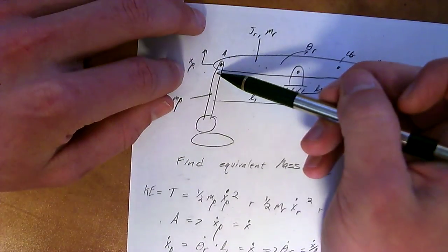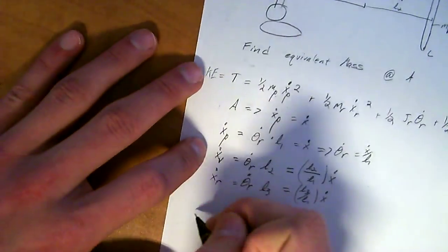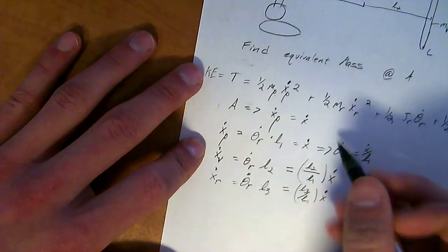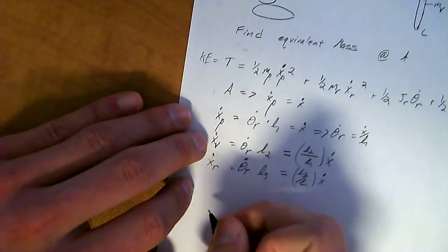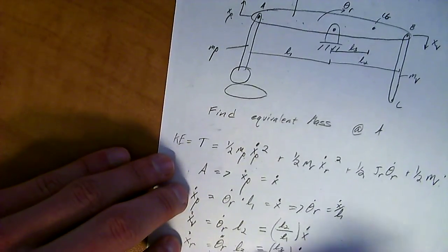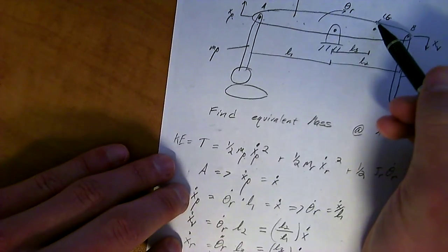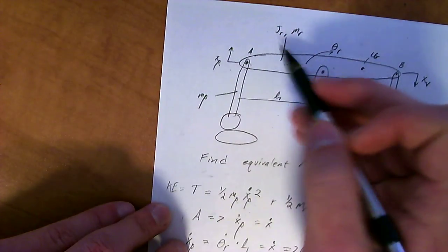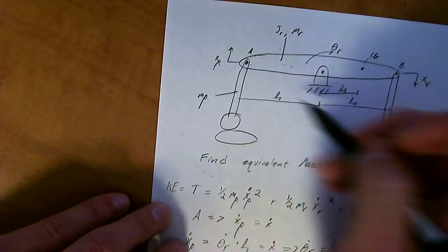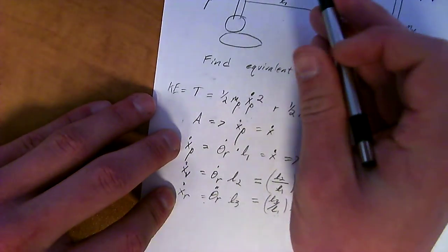Okay, so now we have all our displacements with respect to xp, so we can find the equivalent mass about xp using the energy method. Substituting in these values for theta r, xv and xr into this equation, notice I had xr defined at the center of gravity. That's where you consider the mass of this entire thing, even though it has a moment of inertia, J, over the entire body. You count the center of gravity as the location of where the mass is used.